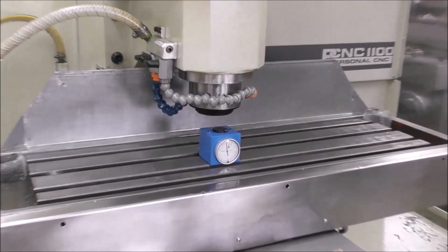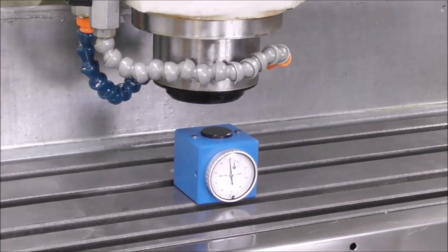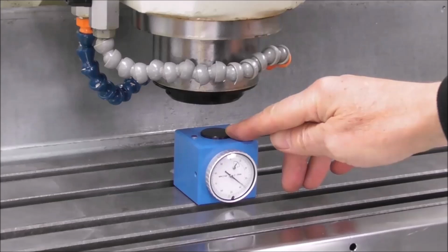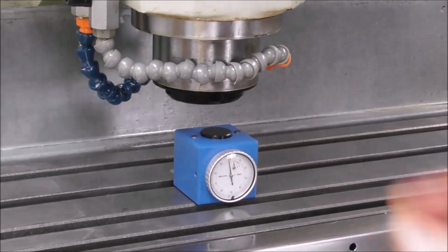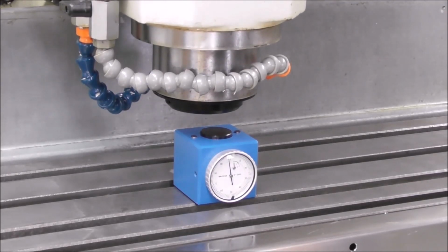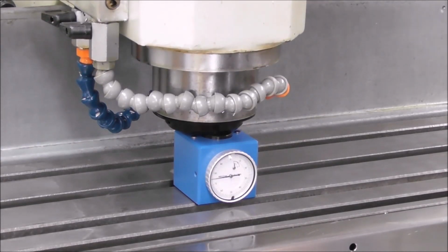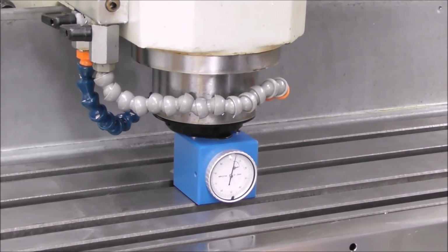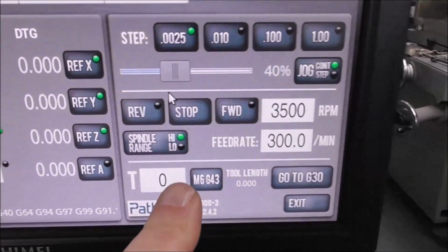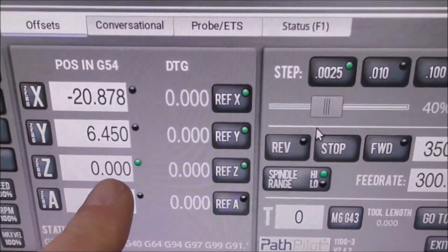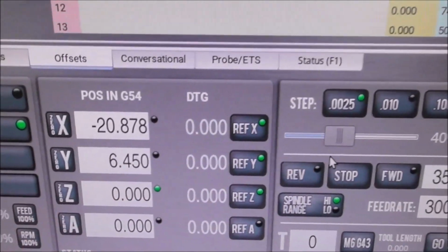So we're going to use a mechanical dial indicator type tool setter. So this type you're probably aware of is like a dial indicator upside down with a large surface on it. So first of all, we'll come down and reference the spindle nose on 0 there, and so we'll have tool 0 set and we'll Z0 out. I'll show you on the PathPilot software in a minute. So that's zeroed that. So on the PathPilot side we just set tool 0, come down to the dial indicator 0 and touch 0 there, so we're on Z0.